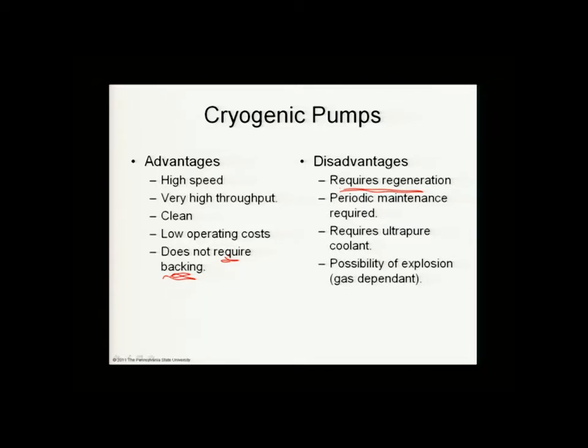As we all know, compressors can give out, like in air conditioning systems. So you have to make sure the compressor is operating correctly, and you have to do a lot of maintenance on the compressor. Now the fluid, for example helium, has to be very pure, and there's a possibility of explosion. That is, you're trapping the gases down there. You have to be careful as you heat the system up, for example, during regeneration, that the gases there don't chemically react. You could even have an explosion.